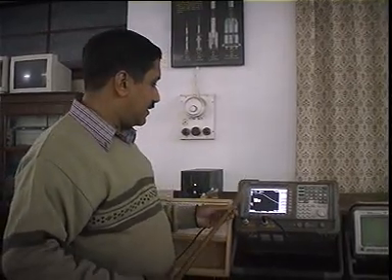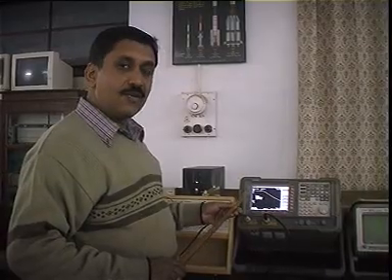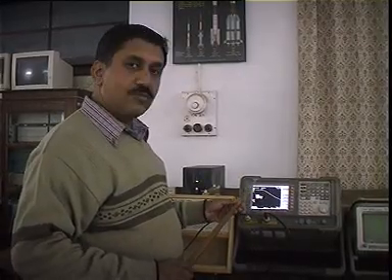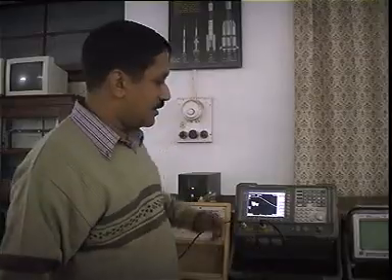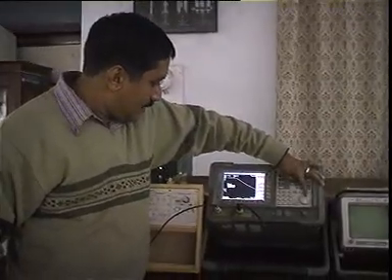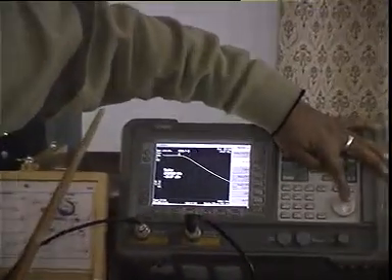That is, the power from the DC value up to a certain value is almost constant. So that is about minus 15.97 dB. If this were to fall by 3 dB, then I would read minus 18.97 dB. The corresponding frequency is the 3 dB cutoff frequency of the filter. So let us move this marker now. It is minus 15.97 dBm.